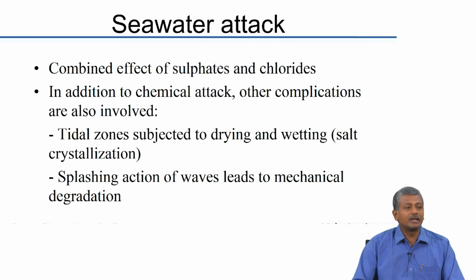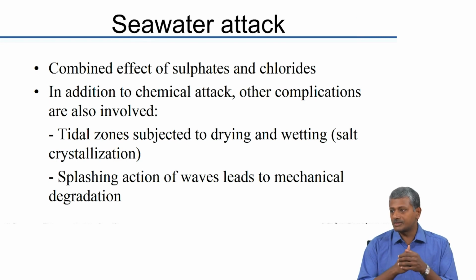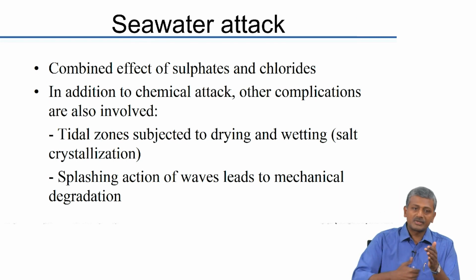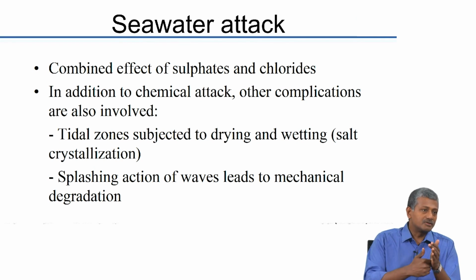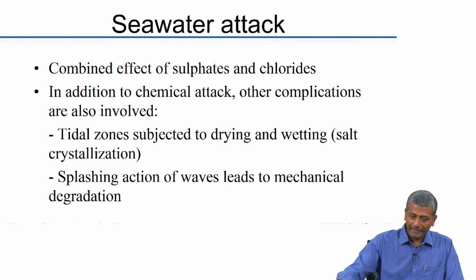So, in addition to this chemical attack, there are other mechanisms that are extremely important. One is the tidal zones which are present in seawater are subjected to drying and wetting. Okay, because of the effect of tide, you will have drying and wetting of the concrete structures that are in seawater, and then you will have the splashing action of the waves that leads to mechanical degradation. So, if the surface is already getting degraded with the reactions with the sulfates and chlorides, the waves are simply impacting the softened surface and trying to remove the material on the surface. So, you obviously have a compounded problem because of the physical degradation.